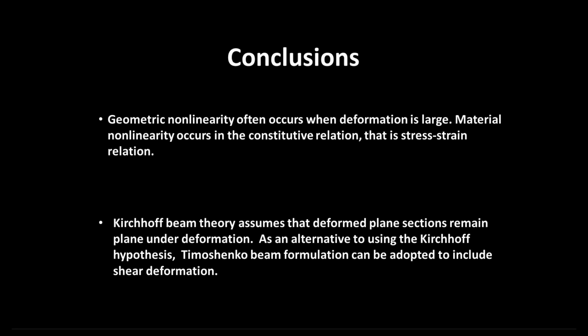In conclusion, what we learned: geometric nonlinearity often occurs when deformation is large. Material nonlinearity occurs in the constitutive relation, that is, the stress-strain relation. Kirchhoff beam theory assumes that deformed plane sections remain plane under deformation. As an alternative to using the Kirchhoff hypothesis, Timoshenko beam deformation can be adopted to include shear deformation.